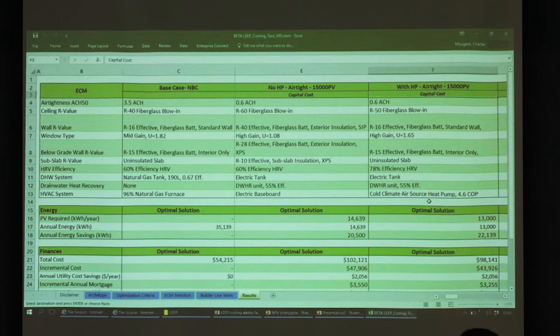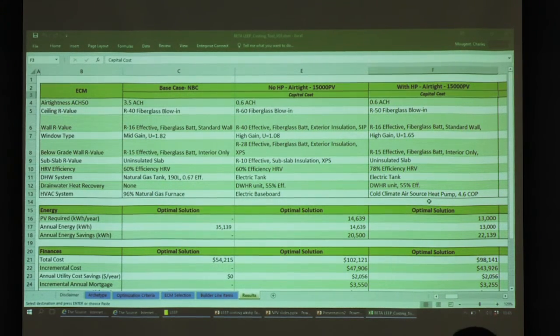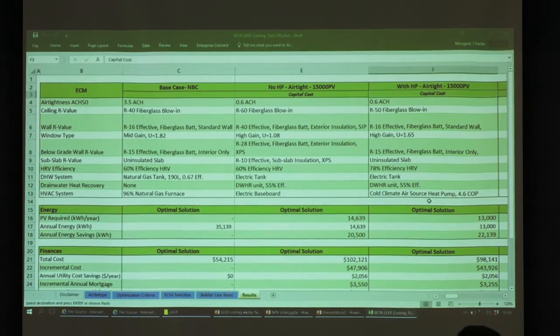A lot of builders these days are opting for hybrid solutions where they have an electric heat pump with a gas backup, so that when you get to -10, -15, the homeowner can decide, or it can even be programmed into the thermostat so you don't have to rely on homeowners knowing the difference. You can set those up to be the most energy efficient cutoff point or the most cost effective cutoff point, based on what you're paying for your gas and when you need it, and what you're paying for electricity when you need it. So it is moving, but yeah.